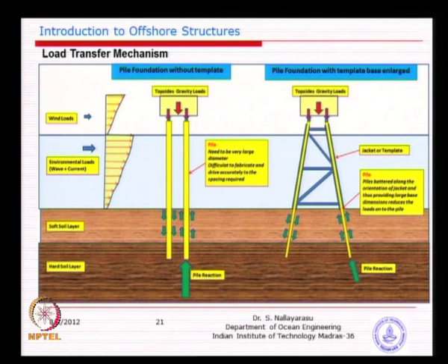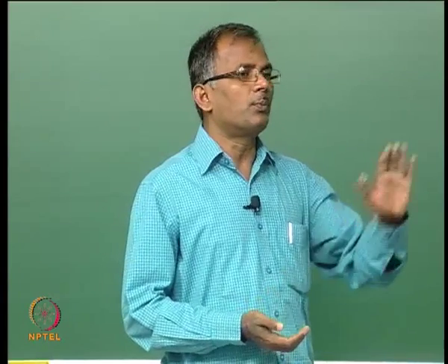You have a tubular or other forms of piles driven into the ground and then you bring and install the superstructure. But one of the problems here is that the superstructure is brought from somewhere, because it is prefabricated, isn't it, because this platform is installed in the middle of the ocean. Now, to fabricate this in that location becomes a bigger worry. So, normally what is done is you prefabricate, mostly not concrete, mostly steel structure, so that you can transport it easily without much trouble and put it on top.